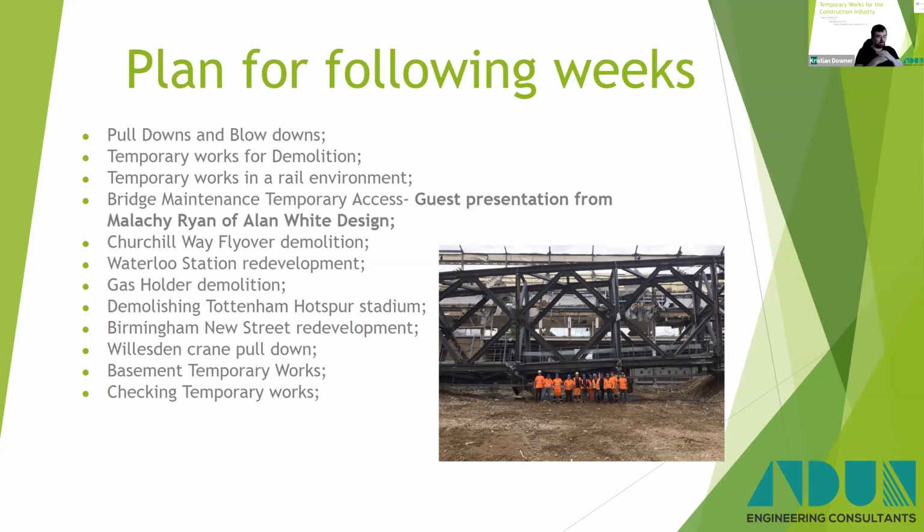We're good. No, look, I tell you what it is. On the large scale data center constructions, you've got a main PC working directly for the client, just the same as most contractors. Well, we will come in standalone to build the backup generation set. Normal thing, the main contractor will be in charge of the site, health and safety policies, procedures, temporary works, lifting procedures, all of that. We fully comply. We have to submit our risk assessment, method statements, our lifting plans 14 days in advance of any works going on. Accept it, not a problem.